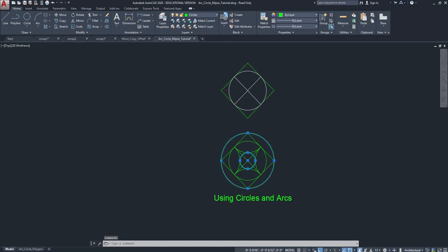And this is going to be, let's see our circle here. Center radius. I can click and I can specify a radius if I want to, okay? But I can also use my mouse to specify a radius. So I can input a number to specify a radius, but I can also use my mouse and visually use my object snaps to achieve that same thing. Click, click, and I've just created my other circle there, okay? So I have my outer circle, I have my inner circle, I have my crossbars, I have these lines that I generated. Really, it's just now I need to learn how to create my arcs, and this circle will just be another 3-point circle inside those arcs, okay?